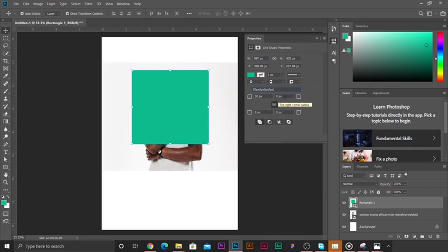These individual fields come into use where you have to make designs in which each of the corner radius, which is what the angles of the edges are actually called, is different. So you come here, remove the link, and put in different numbers for each corner radius.